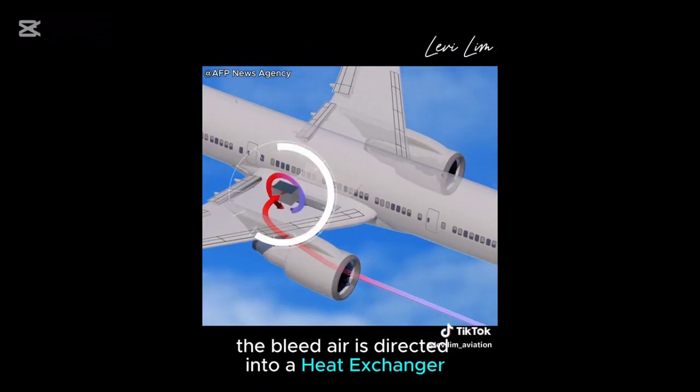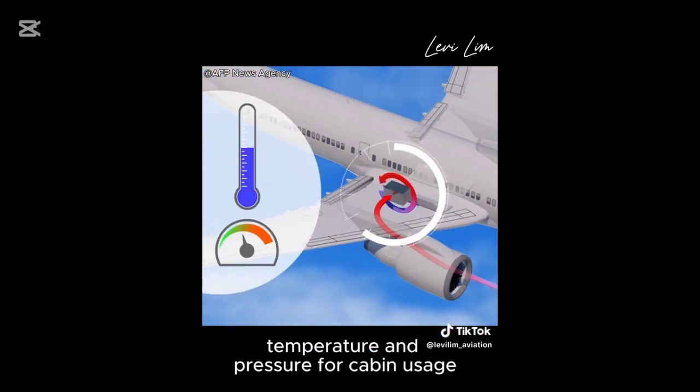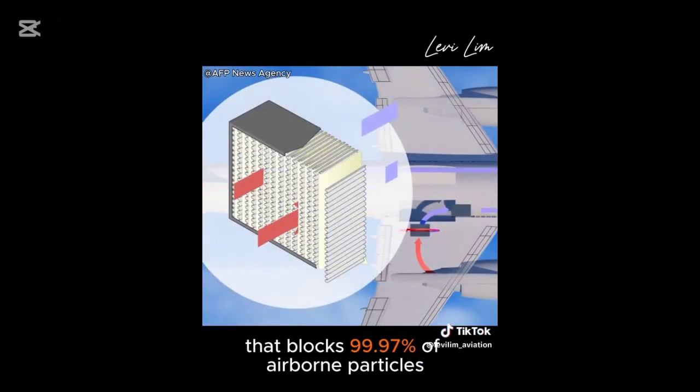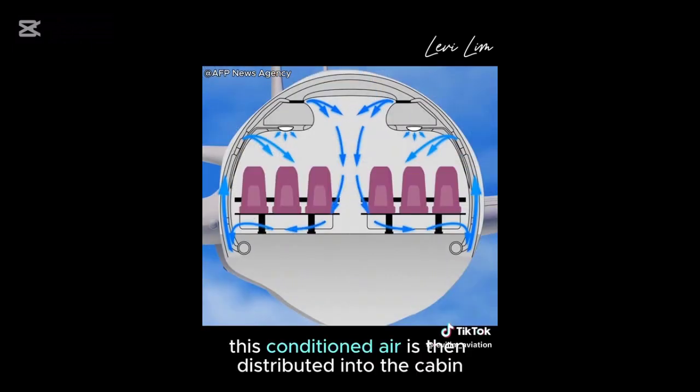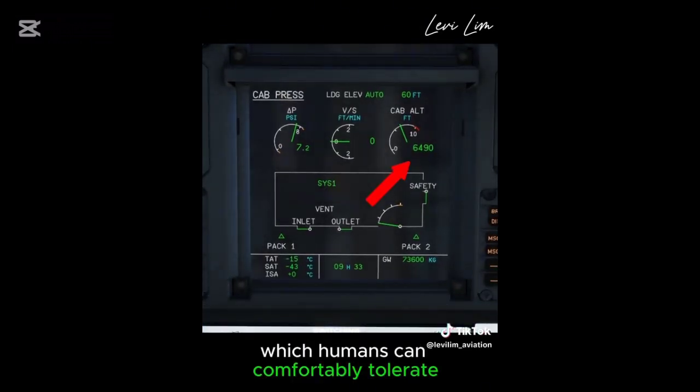The bleed air is directed into a heat exchanger. This cools down the hot air to a suitable temperature and pressure for cabin usage. The air is then directed through HEPA filters that block 99.97% of airborne particles. This conditioned air is then distributed into the cabin. Aircraft cabins are normally pressurized to an altitude of 6,000 to 8,000 feet, which humans can comfortably tolerate.